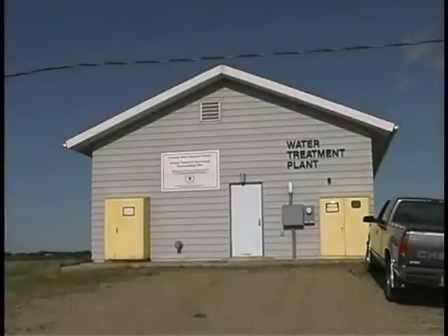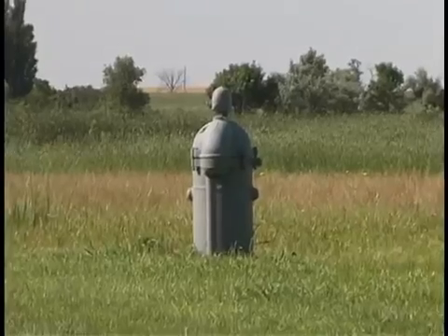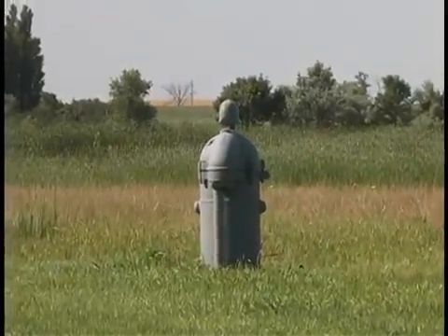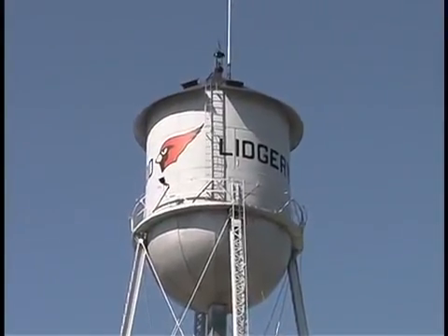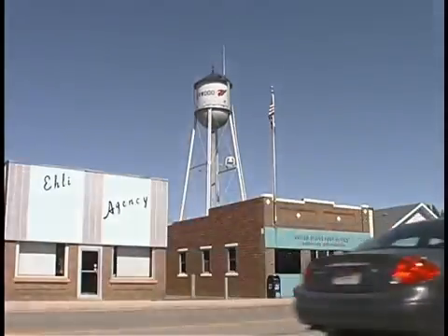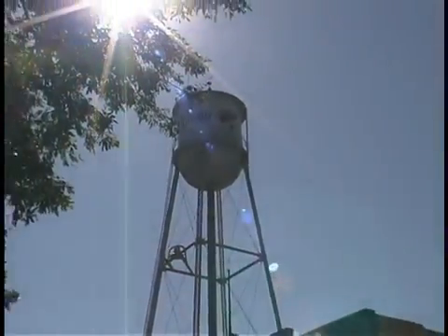The source water for the community is 2 wells. Each well is used for 1 month, then the other is used. The wells produce about 250 gallons per minute each and are about 100 feet deep. The community uses between 80,000 gallons per day and 160,000 gallons per day. Normally it'll run about 2 hour stretches, and she'll probably run about 6 times during the day for 12 to 14 hours in a 24-hour period.